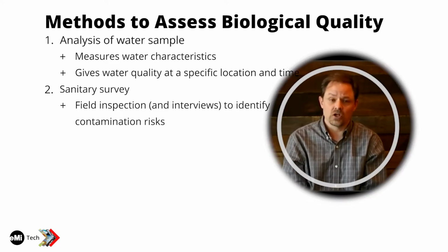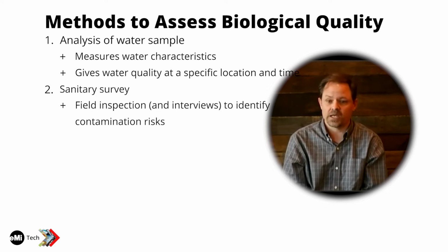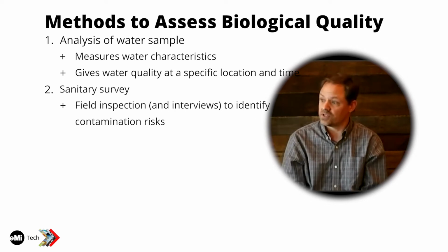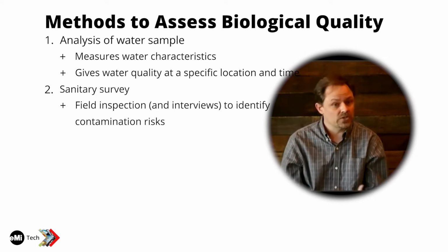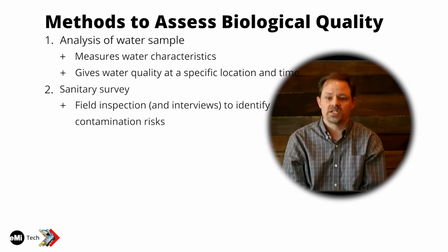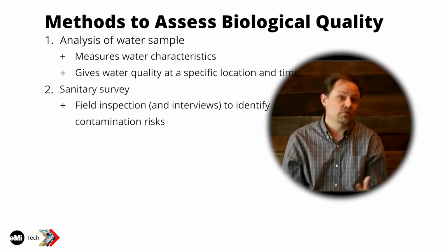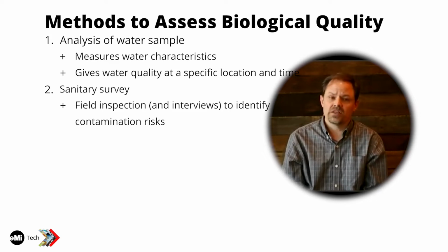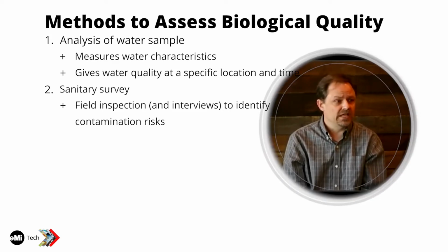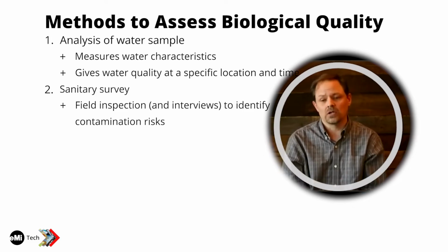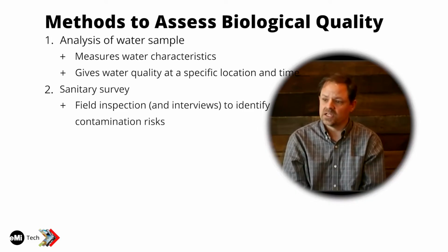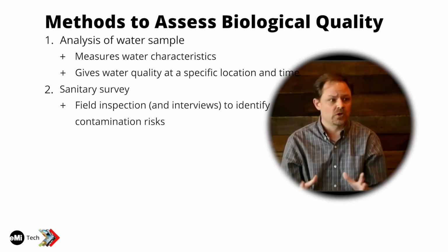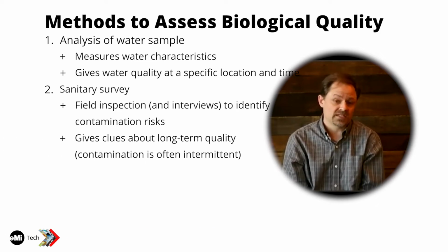And also a good supplement to that field inspection is interviews of community members and the operators of the water system, to learn from what they've learned about the system. And really the purpose of the sanitary survey is to extrapolate what we learned from those water samples to get a broader sense of what's going on with that system.